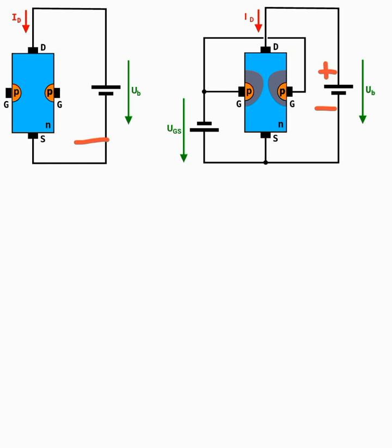But now in the picture on the right you have a battery applied to the gate with respect to source, where a negative voltage is applied to the gate of the transistor as shown. Remember, I said the gate is common, so on either side of this N-type semiconductor you have gate pins, to which the negative potential is applied, and the positive of this battery is connected to the source.